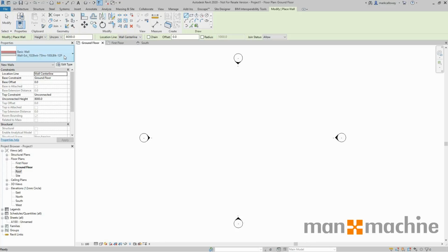Although Revit is a 3D application, a lot of the work that we're going to be doing is going to be in 2D views. So if you come from a background of CAD applications such as AutoCAD or ArchiCAD, we're going to be using some of the similar processes here. Looking at our draw tools, we've got items such as drawing lines, rectangles, polygons, circles, arches. There's a few extra things on here.